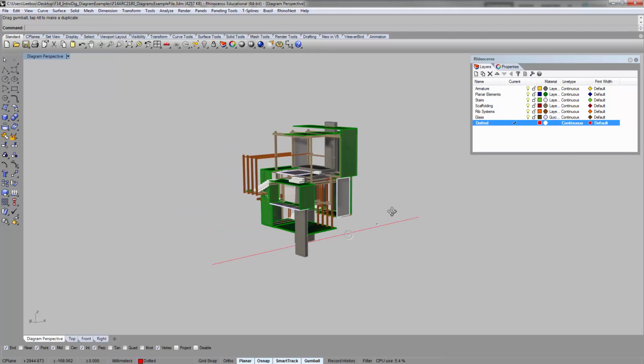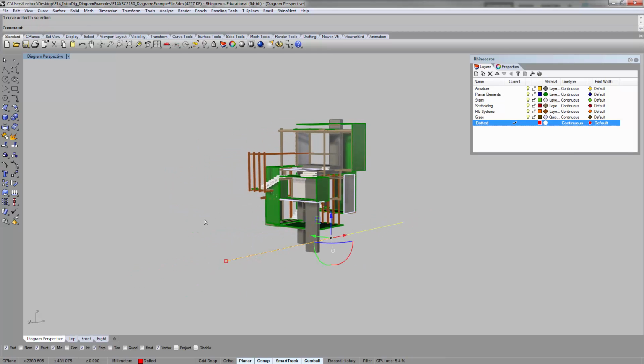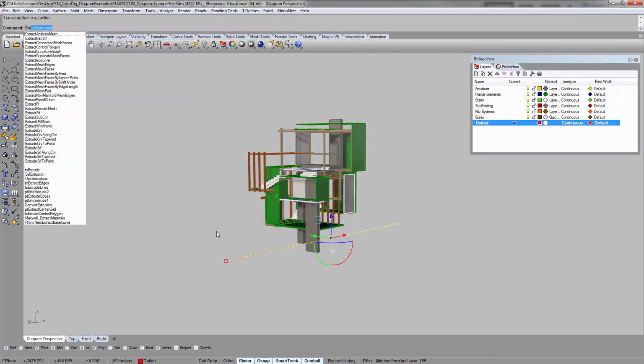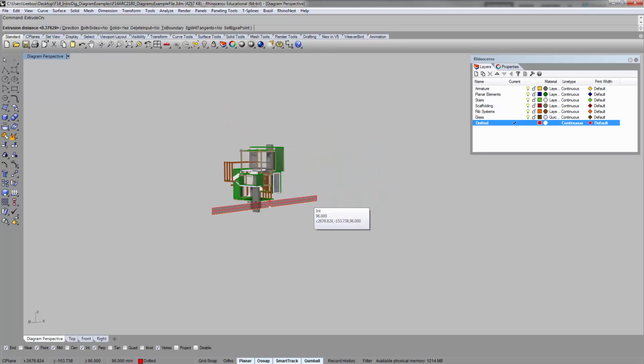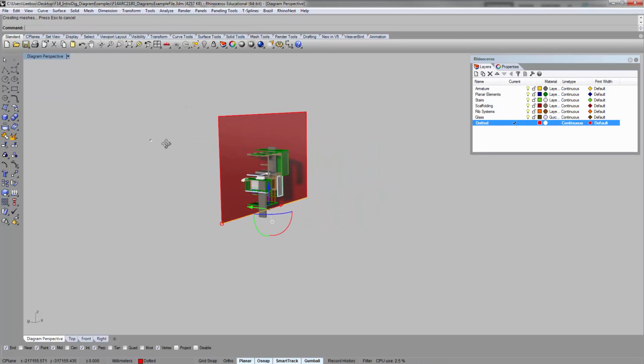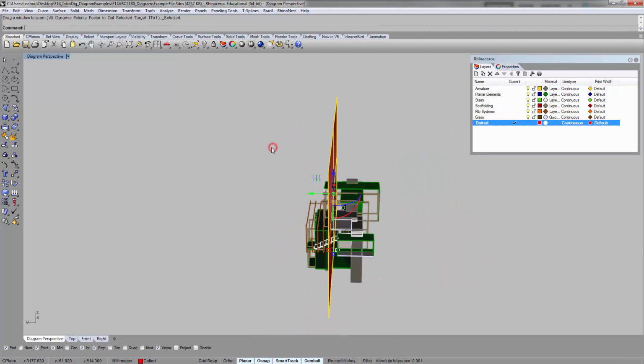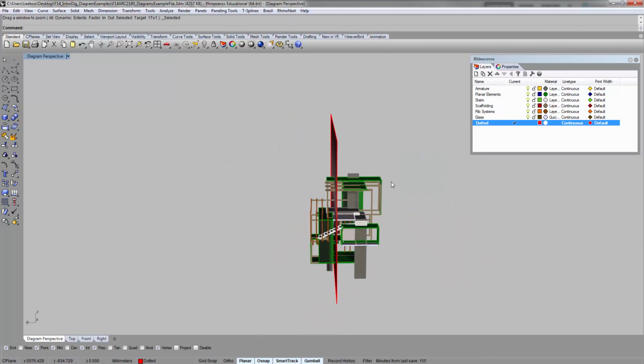The technique is the same, except you extrude this. Just do the extrude curve right here. If you drew a straight line, it will automatically make you a plane like this, right? And you can split this and it'll give you two halves, right?